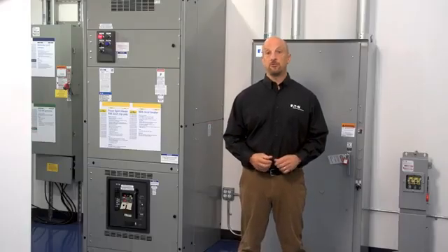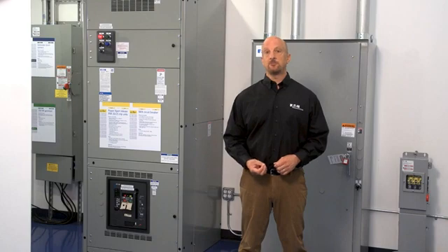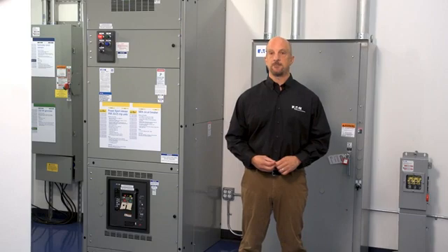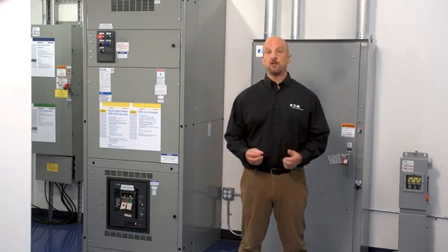Modern medium voltage breakers use vacuum bottles as the mechanism to break current during an overload or fault condition. The components are similar to the low voltage power circuit breakers, except the vacuum bottles replace the arc chutes and contacts. Protective relays provide tripping logic for medium voltage breakers.